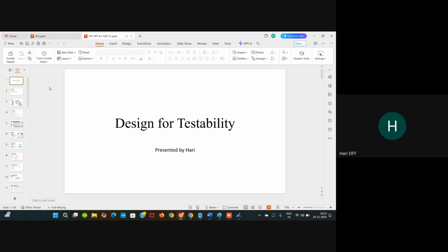Most people have an assumption that DFT is meant to test the functionality, but it is not. But DFT, trust me, indirectly tests the functionality. Until and unless the logic is correct, we can't simulate the design. Because we DFT people usually simulate the test vectors after completion of scan insertion.